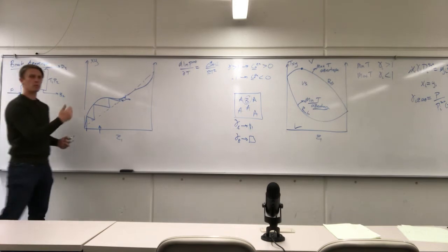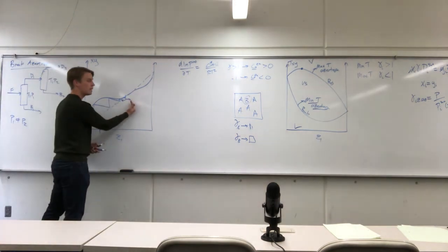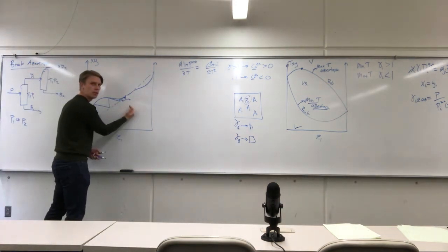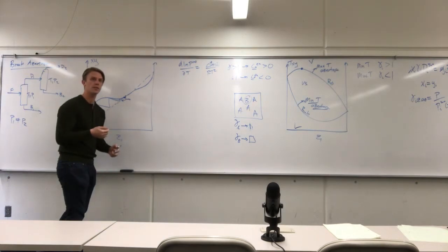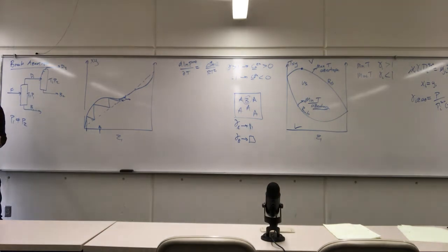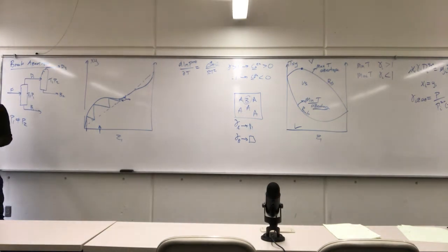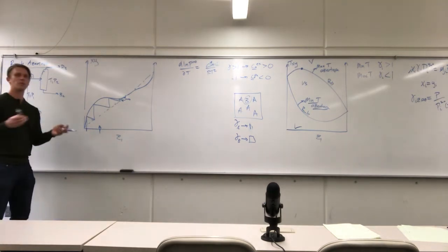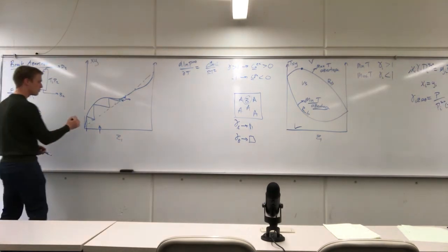The more of a pressure swing that you do, the more you'll move the azeotrope. But the more pressure swing you have to do involves changing the pressure significantly in your process flow stream. The less pressure swing you have to do, the more stages you have to have in each of your columns in order to break that azeotrope. Right, so it's an engineering problem. There's the reason why chemical engineers get paid a lot of money, right?